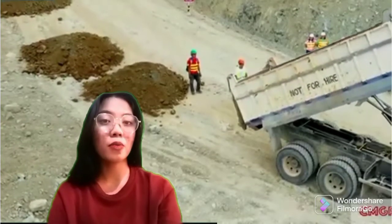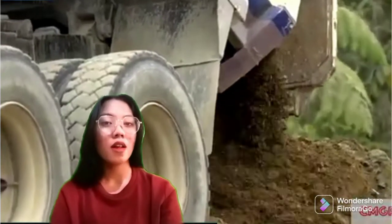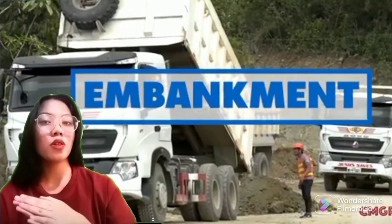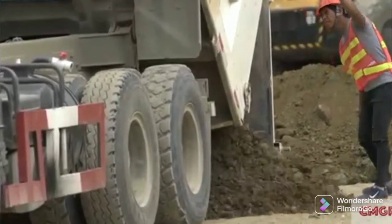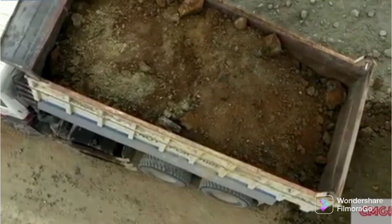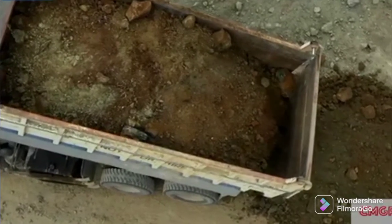For excavation, the situation is that the place of road construction is higher. In the situation where the place is lower, the application will be embankment. Just like in clearing and grubbing, here in embankment, the soil that is used should be clean, with no biodegradable or organic materials.